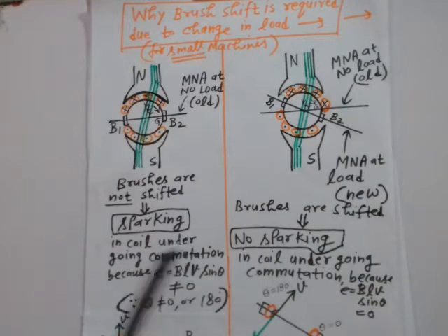So now our aim is to understand why brush shift is required due to change in load, right? So the answer is to avoid sparking, right? To avoid sparking at the brushes and the commutator surface. So here, see how it can be avoided by brush shift.